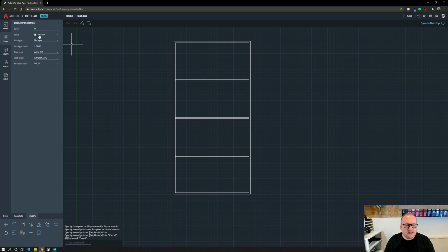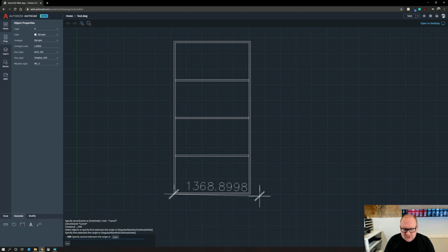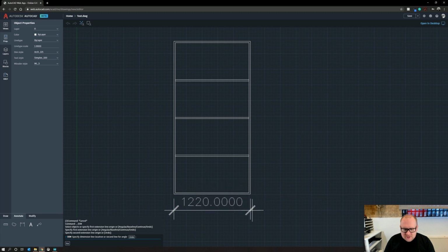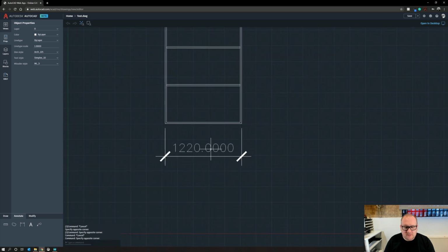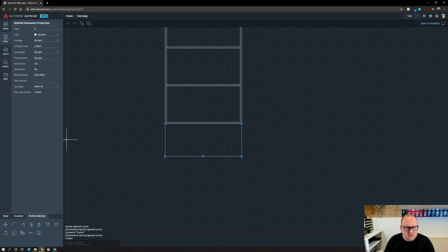The disadvantage of this is when I go to properties or to then do some dimensioning. In fact, if I go to the annotate tab, I think it will just give me a generic annotation that it thinks is the right size, which you can see is huge. And I don't get much in the object properties, much option to edit, although they've built in some simplex, which is basically the simplest form of dimensions that they will create. Let's just see if we can change that to mechanical 10, see what it does.